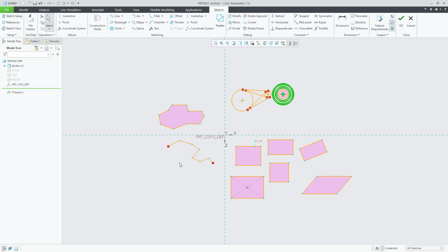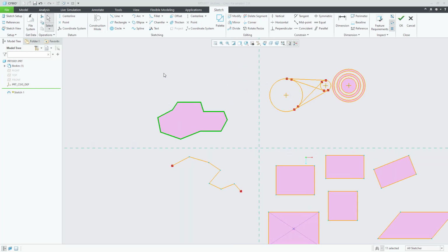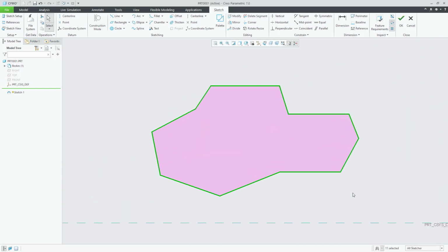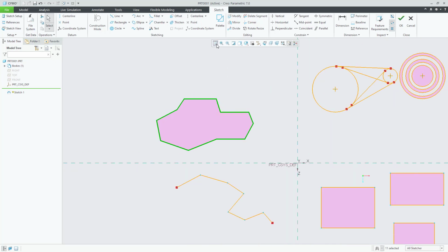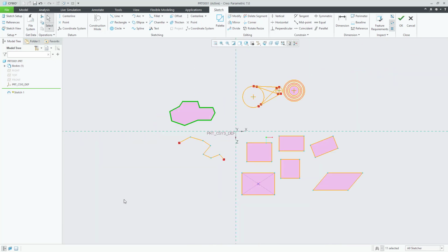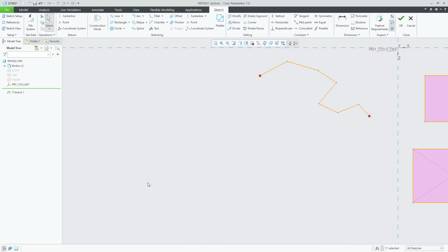Whenever you want to zoom in on a sketch, let's say I want to zoom in to this sketch, just select this sketch and you'll get a window over here, and you can see a small option given over here with the pointer and a magnifying glass. Just click on it and it will zoom only to that sketch. Just fit it to the window and I'm going to zoom it over here.